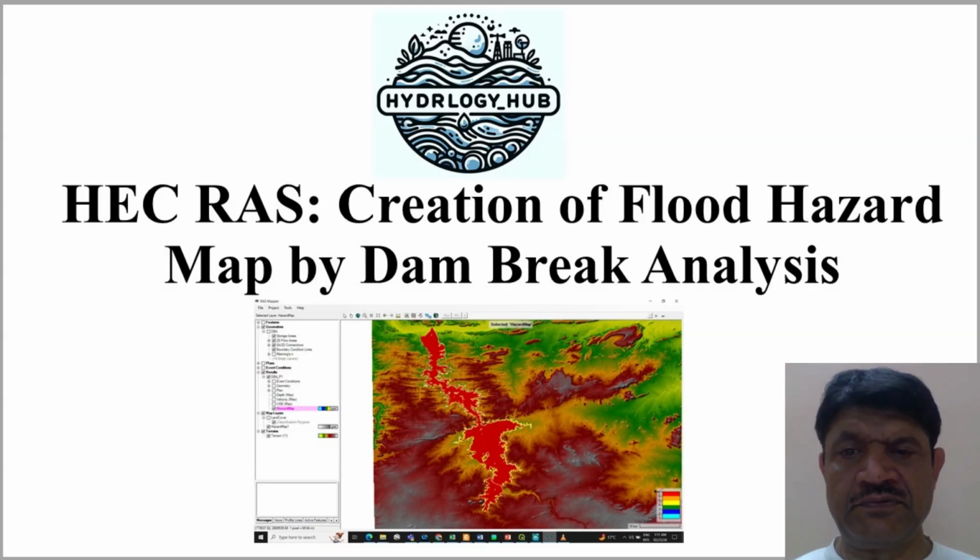The dam hazard potential classification is a direct result of flood hazard analysis of different scenarios that can occur. However, one of the challenges in this type of assessment is the fact that the degree of hazard varies with the severity of the flooding and is affected by the flood and its hydraulic behavior, the topography, population at risk, and emergency management.